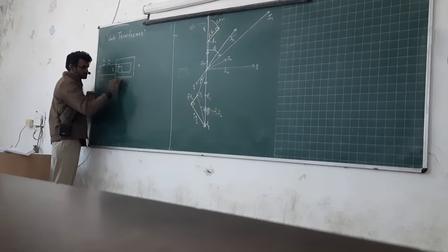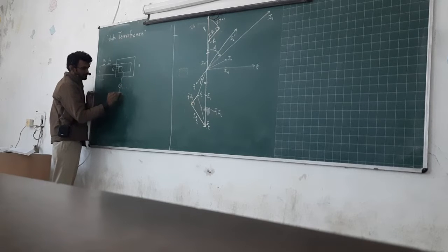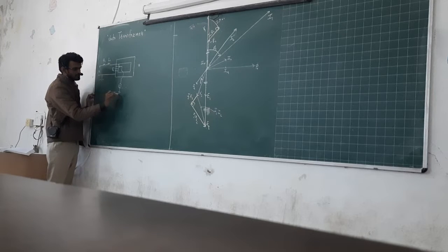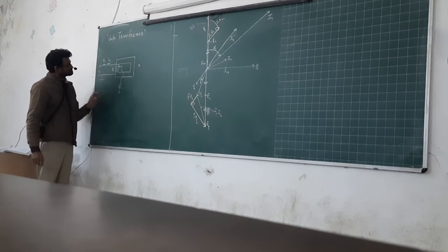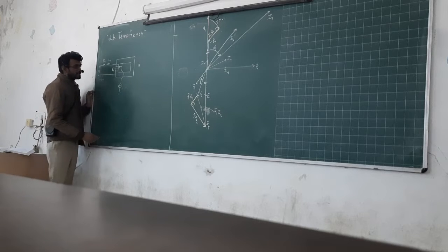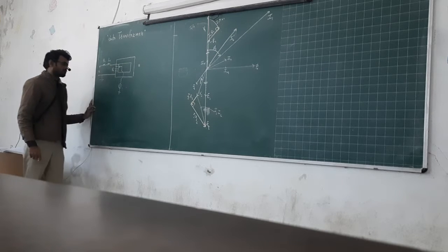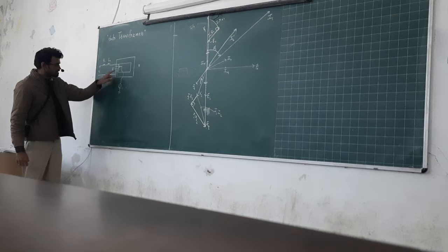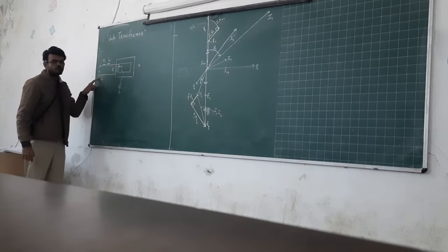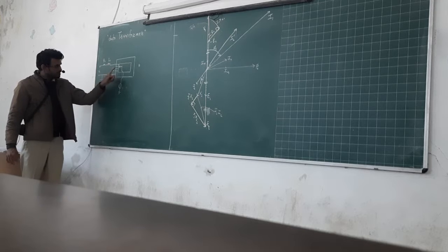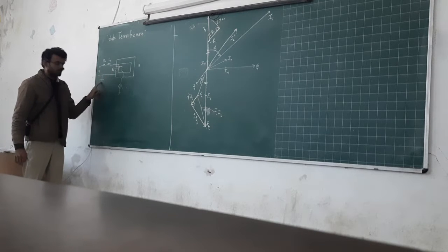And this voltmeter here is connected with the ground. So these two things are connected. You can see that. These two things are connected. And if I change the position of this pointer, then what will this voltmeter measure? It will measure the voltage between this point and 0. This is the ground, so it is 0. So that will measure the voltage between this point and that point.